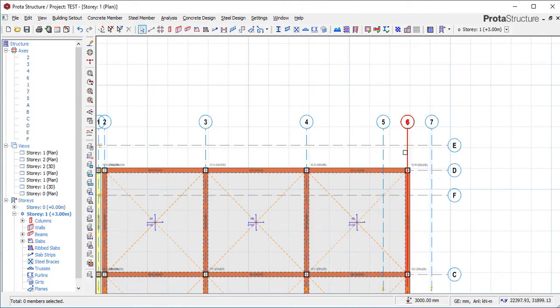So once you've done this, you've created, like what Linus, your question is, I'm having a bit of challenge of setting the grid lines. So with this, you've been able to do your grid lines. Then your question also said, I face this challenge when having floors with different general arrangements where some columns do not run from foundation to the roof. It was easy with Orion. Also, the challenge of columns taking off from cantilever slab. I kept getting columns not supported.